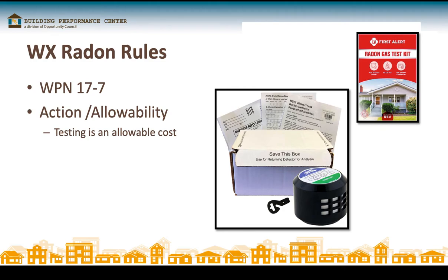What they're probably going to do is their precautionary measures, and these precautionary measures are required in closed crawl spaces and in basements. So if you have a vented crawl space, it's not required. If you have a combination basement and crawl space and that crawl space is closed up, you've got to do the precautionary measures. But if you have a vented crawl space that's attached to the basement, then you have a vented basement, so you're not required to do the precautionary measures.